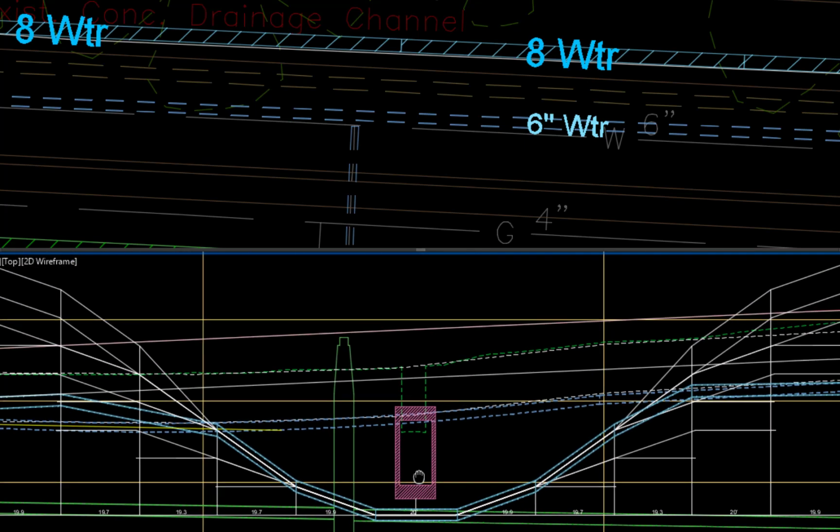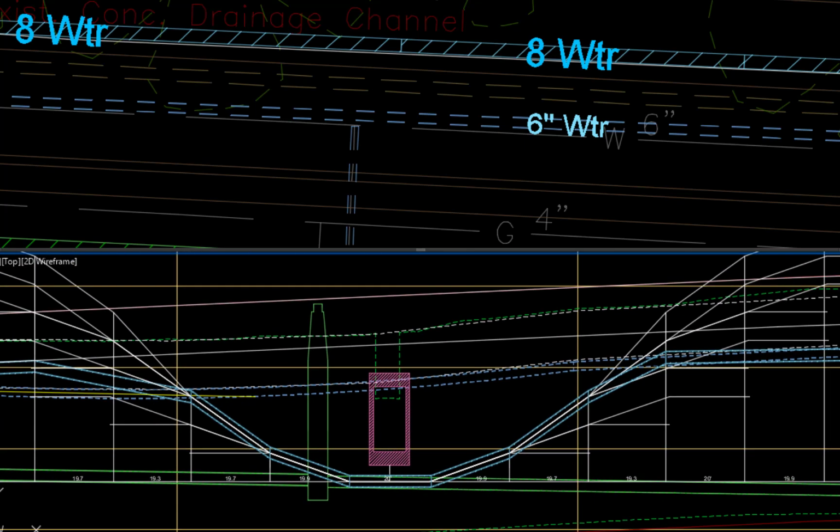Escape. During the installation, the pipe needs to be inserted in line with the previous pipe. The pipe is deflected after the joint is made. The pipe deflection offset distance for a 20-foot section of pipe is 20 times the sine of 5 degrees, which is 1.74 feet. It is generally left up to the contractor on how he wishes to perform the work for